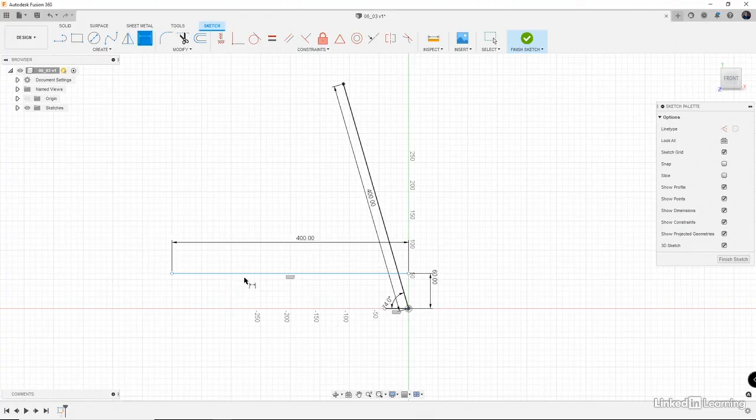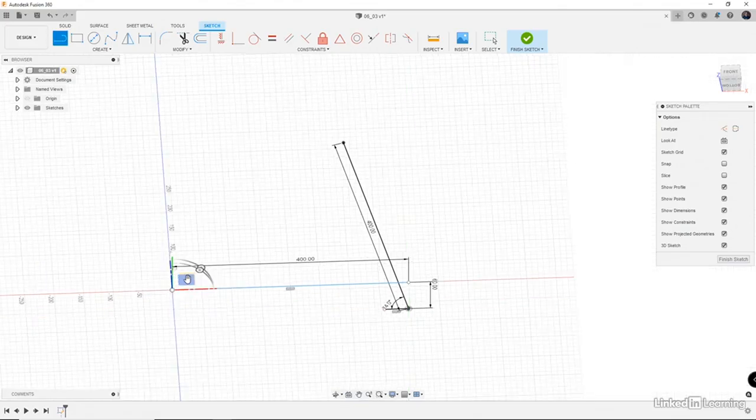So now once we have this set, this is the axle of our rear wheel. I want to come towards us a set length so that I have geometry of where I want the axle end to be. So I'm going to hit escape and use the line tool. I'm going to select this endpoint here. Then I am going to orbit over here and select this construction plane. I'm going to snap it to the axle here, and I am going to come out 71.25.